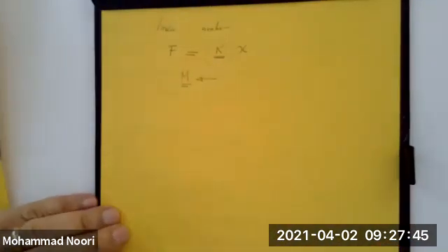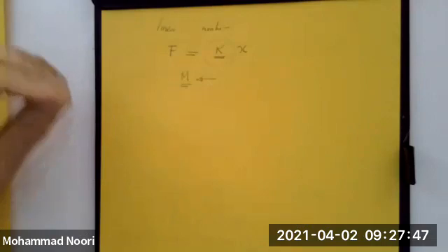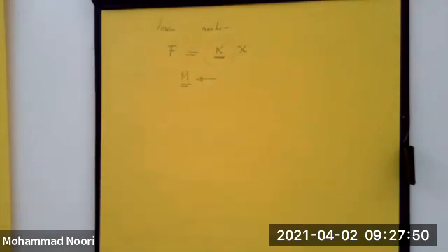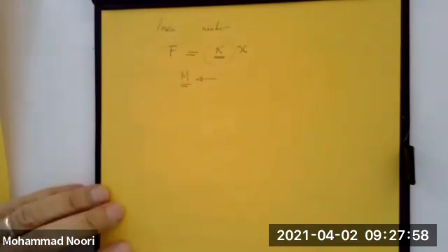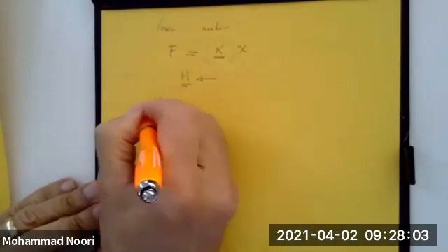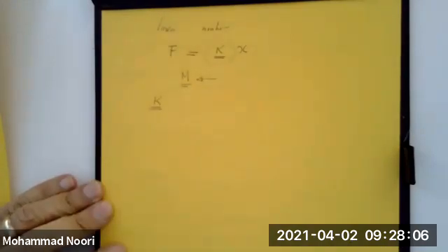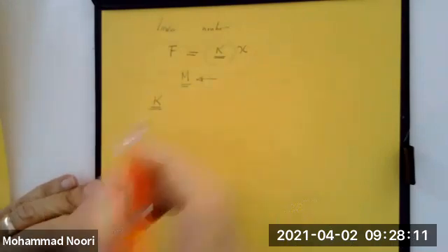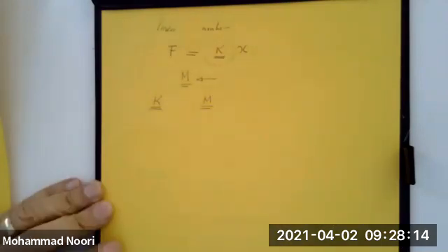So far, in all the courses in engineering mechanics that you have studied, you have only experienced two of the characteristics of a real world structure. These two characteristics have been either the stiffness, which is a measure of the ability of the structure to resist deformation, or the mass, which is the ability of the structure to resist motion, which we call inertia.